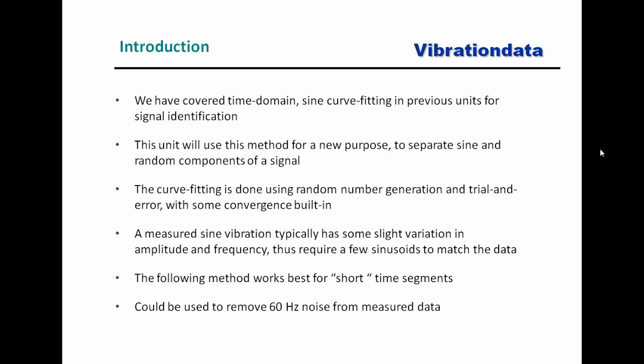There could be electromagnetic interference, for example. Ground loops can occur. If there's a test with multiple power cables and other sensor cables, and those cables are bundled together, that can induce eddy currents or crosstalk, or just some sort of electromagnetic interference.